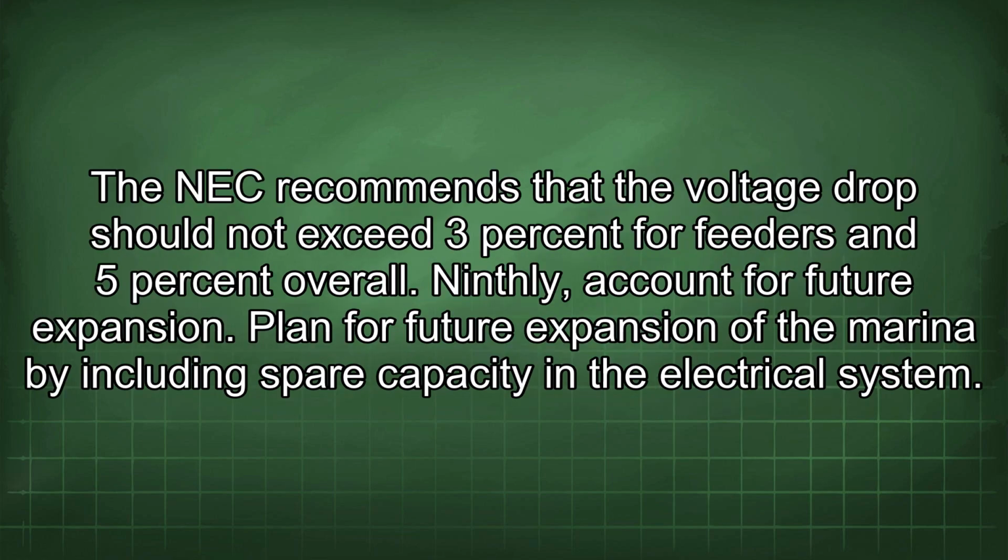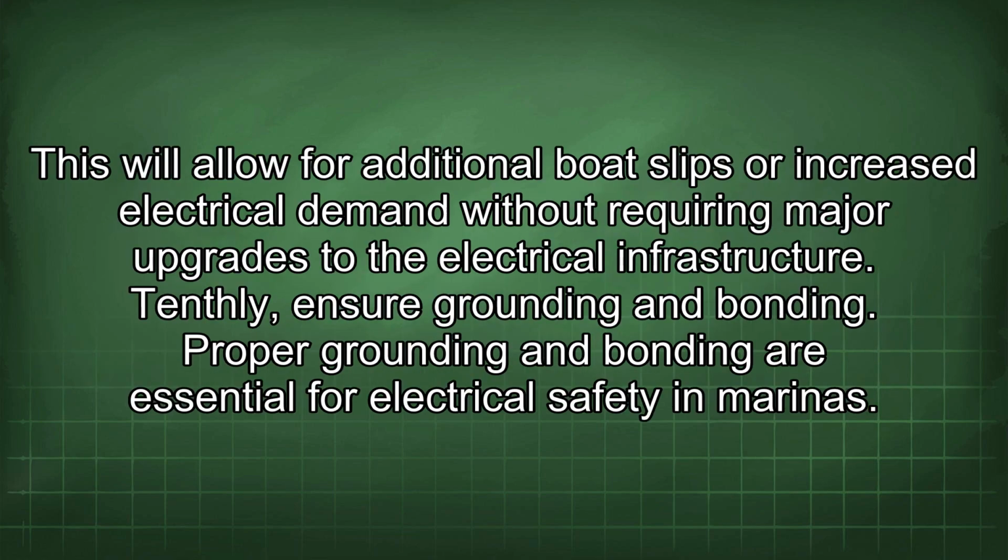The NEC recommends that the voltage drop should not exceed 3% for feeders and 5% overall. Ninthly, account for future expansion. Plan for future expansion of the marina by including spare capacity in the electrical system. This will allow for additional boat slips or increased electrical demand without requiring major upgrades to the electrical infrastructure.